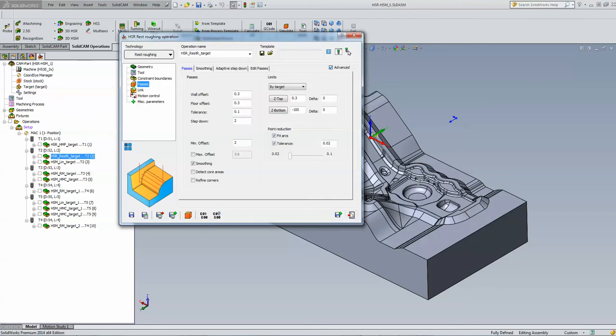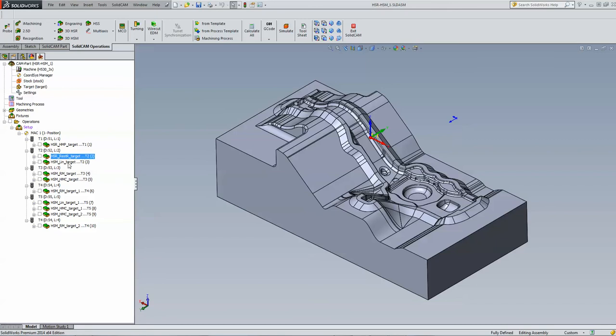Now, let's go into HSM now. Like I said, when we machined this part, we wanted a really nice finish. So when we machined this, we said, okay, when you're working on a really nice finish from a roughing cut, you first want to do some semi-finish operations. So what we've done is in the first operation of my semi-finish, actually stage 1, because we actually did two levels of rest rough of semi-finish to get as close as possible before we did the finish itself.